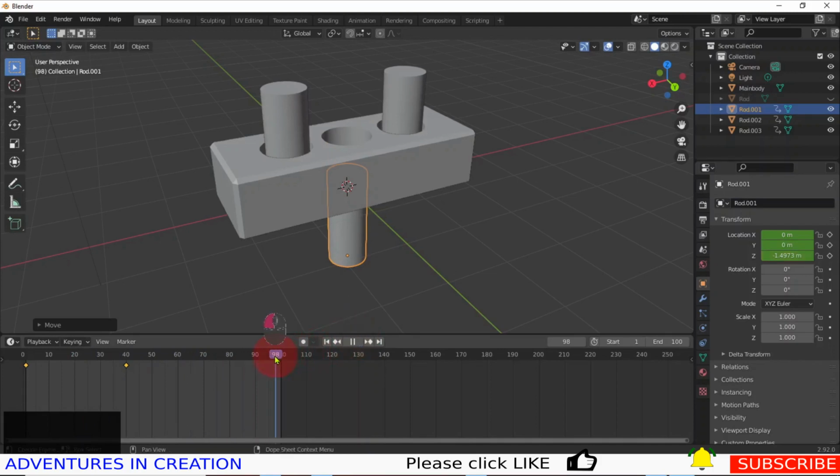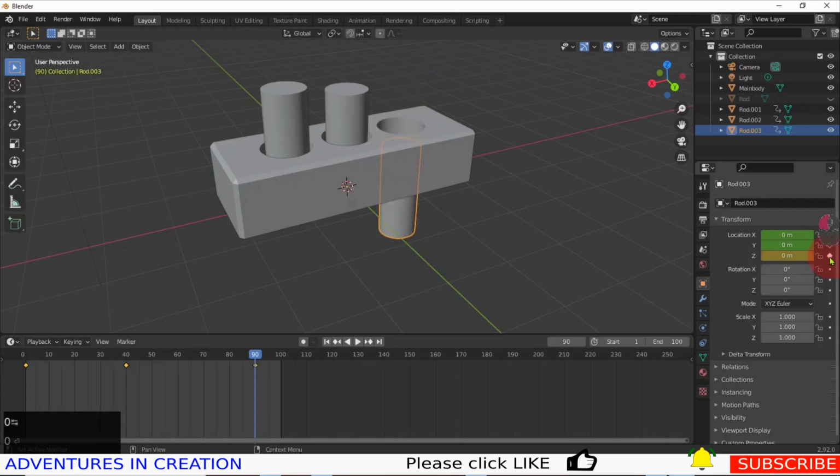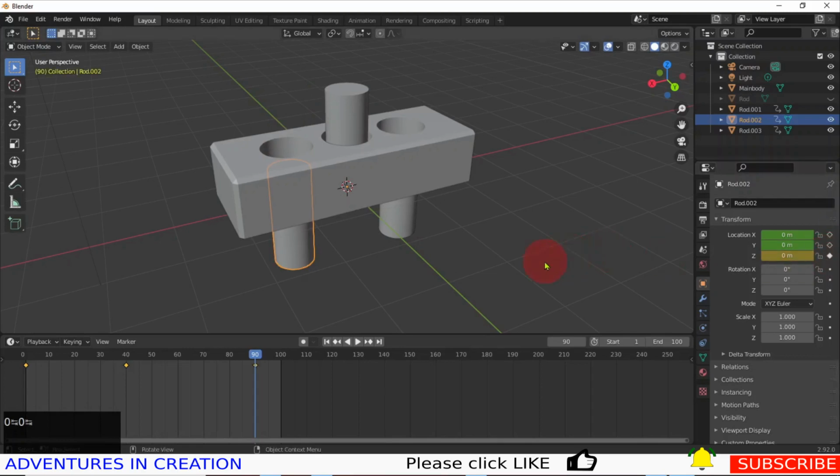So we can say, move this to 90 and simply change this to 0 and hit the keyframe. Select the next one, change that to 0, hit the keyframe. Select that one, change that to 0. Remember, we started at 0, so we know that's back where we started from.